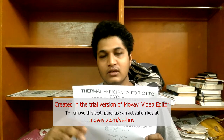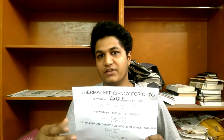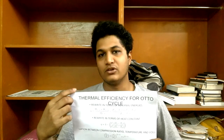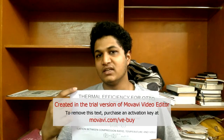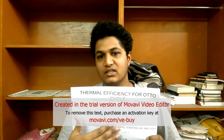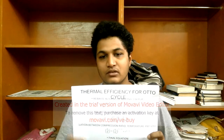I said before that heat is always added or rejected at constant volume, which means that the heat constants can be defined as heat capacity at constant pressure and at constant volume, which are Cp and Cv, as you obviously know. Cp over Cv is gamma, and Cp minus Cv is the gas constant R. So after knowing that, you can write eta in terms of Cp and Cv, but we will only write it in terms of Cv because we only have constant volume processes involved in the Otto cycle.